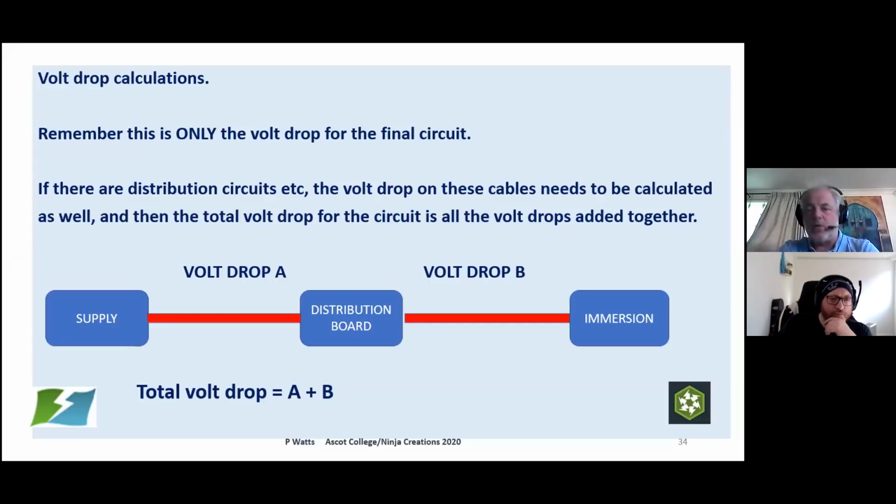So if you know that you're operating in a low temperature, you may want to say to yourself, "Oh, hang on, this is going to affect it." There is actually a factor of 0.004 per degree C. That's a resistance value. Every degree C that your cable temperature increases or decreases, it affects your resistance by 0.004 ohms.